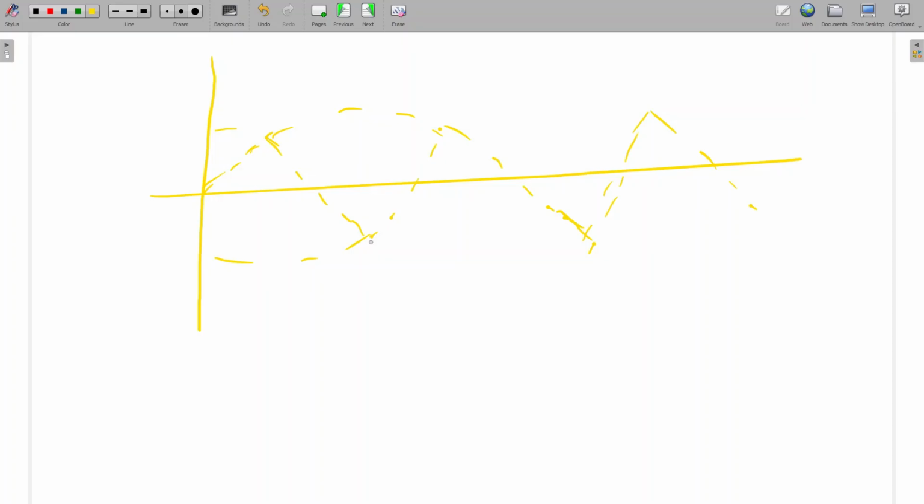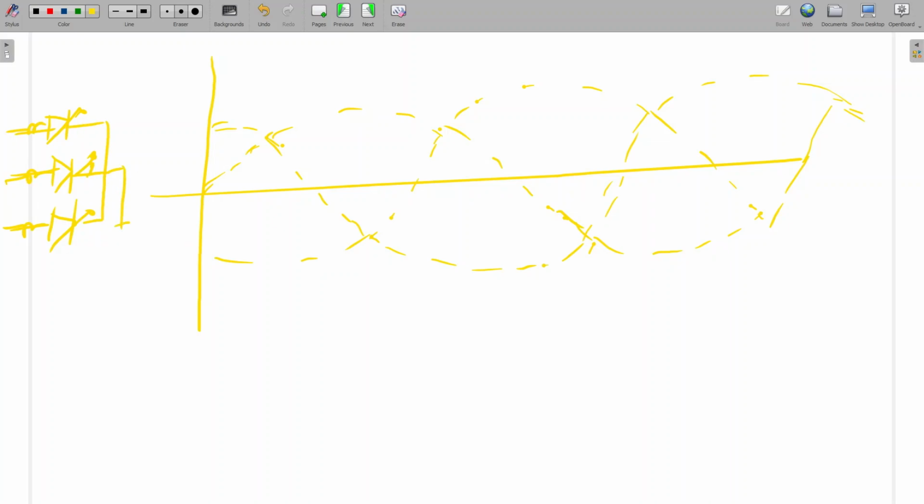So in this way, in the exam, if you want to draw the waveform, you can first draw the dotted line, and then you can join all the adjacent tips. This will be just the reference voltage. If there are three, 3 thyristors will be there, and with every thyristor, 1 inductance will be there. So if the effect is not there,